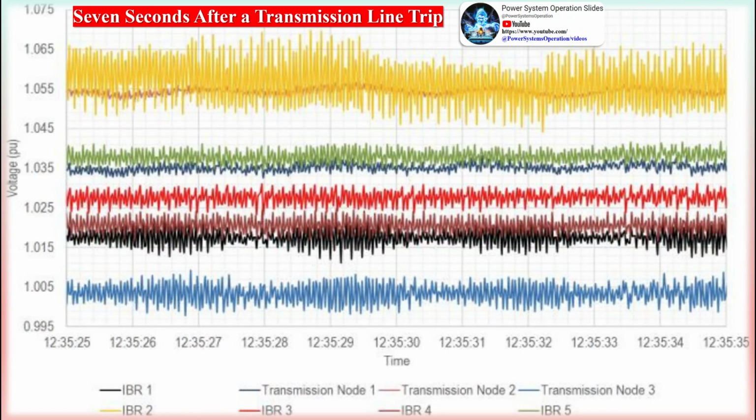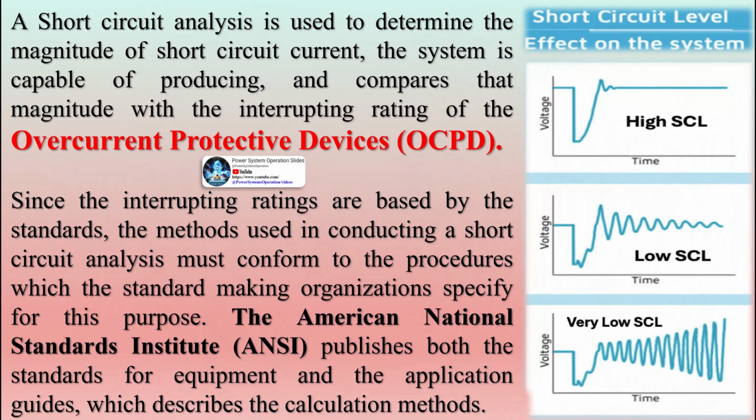This process is disrupted when there is a fault on the grid because the voltage waveform becomes unstable. After the fault is cleared, the inverter must relock onto the grid quickly to ensure stable control. If the system strength is low, the phase angle change between the pre-fault condition and fault clearance will be larger than on stronger systems, making this process significantly more difficult. If the voltage phase angle detected by an inverter is inaccurate, the current will be injected incorrectly, adversely impacting the voltage waveform of the grid, which in turn increases the current injection error, potentially creating a cascading impact with widespread disruption to the grid if not corrected.